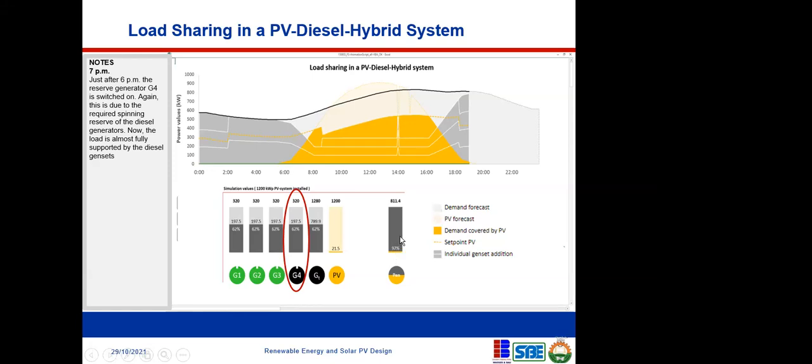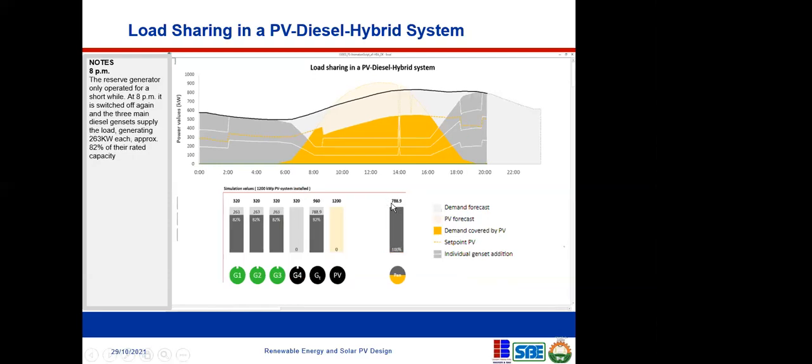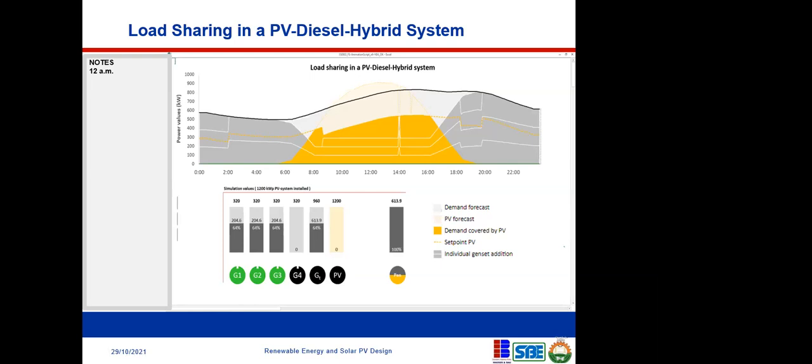It's now 3%. And then if you notice, we have 811, and then it's now dropped to 708 something. So the fourth generator quickly went off again because these three generators can handle that. It went off and transferred its load back to these three generators, and it is 100% generator now. All of this is what a controller does. You can now see that the load is beginning to reduce again, and the capacity of these generators keeps going down as the load goes down.